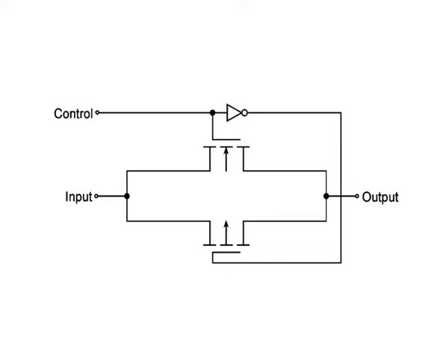Either of the two can be treated as the input terminals for the purpose of applying input. This is made possible by the symmetry of the two MOSFETs. It may also be mentioned here that the on resistance of a conducting MOSFET depends upon drain and source voltages.